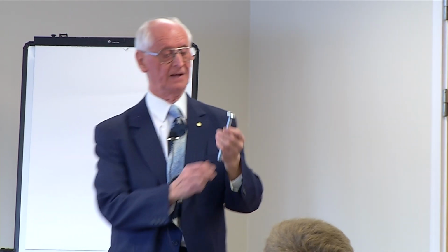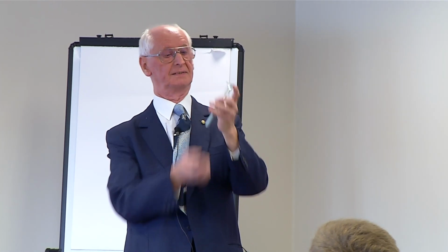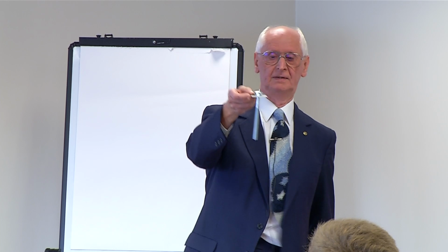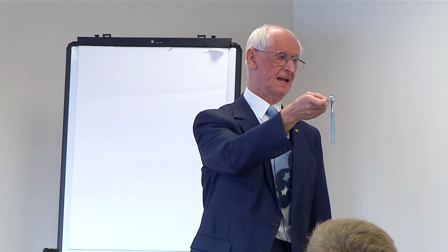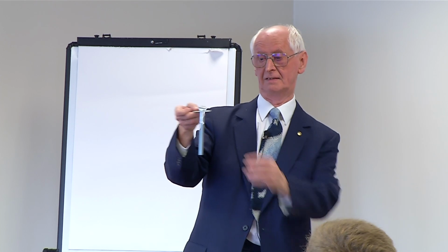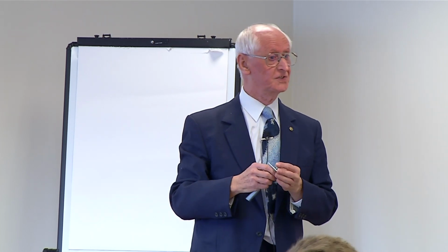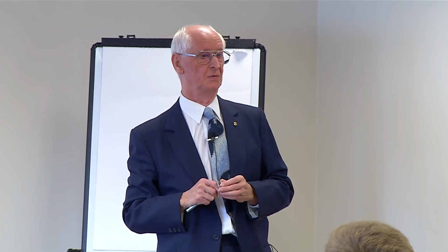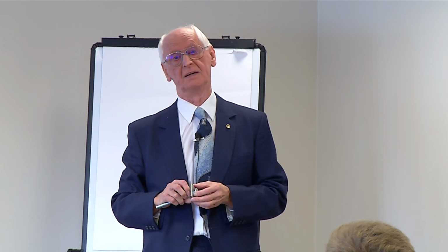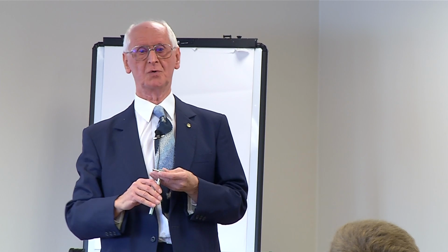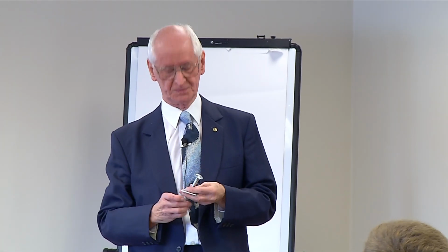There is another problem. Underneath the head is a square section. If you put a square section in a round hole, it doesn't work. The head never actually gets into contact with the washer. Now, you see these in roofs. I've seen lots of them in roofs. I've seen them in all sorts of other structural applications where they should not have been used, and we've had to go in and replace them. And that is a much more difficult problem than putting the right bolt in the first place.